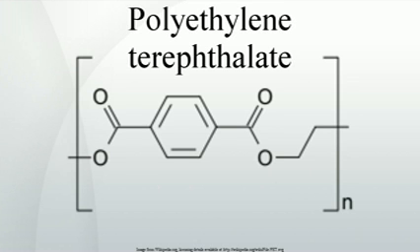This aim is solved by degrading the PET bottle flakes, already during their first plasticization, which can be carried out in a single or multi-screw extruder, to an intrinsic viscosity of about 0.30 dl/g by adding small quantities of ethylene glycol and by subjecting the low viscosity melt stream to an efficient filtration directly after plasticization. Furthermore, temperature is brought to the lowest possible limit. In addition, with this way of processing, a chemical decomposition of the hydroperoxides is possible by adding a corresponding P stabilizer directly when plasticizing.